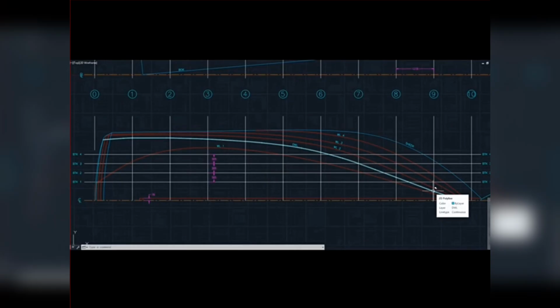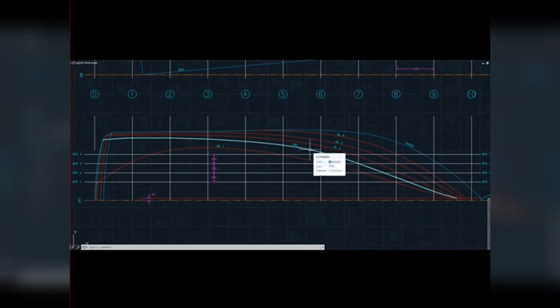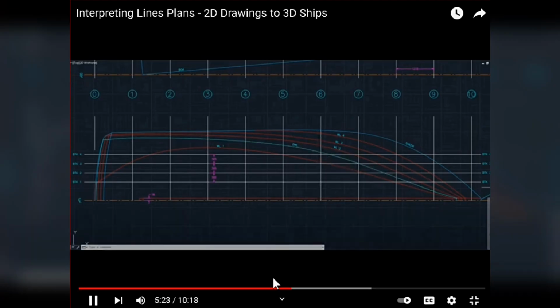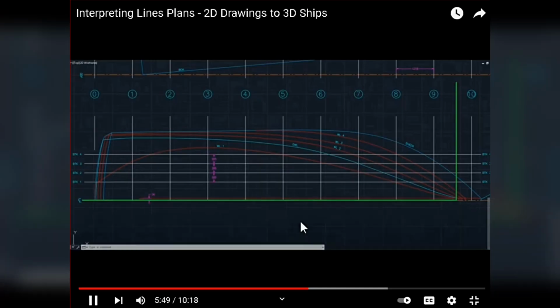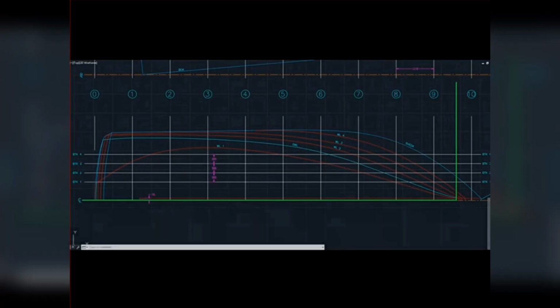Now, of course, I mentioned earlier the DWL, which we're very interested in, because this allows us to calculate a bunch of really important hull coefficients. So things like the water plane coefficient, this is where we're going to be calculating it. It's also very interesting to note that if you look at it carefully, you'll notice that essentially I've created an X and a Y axis, and then I can estimate the water line using something called the trapezoidal rule. But that's also something similar, estimating the area underneath.